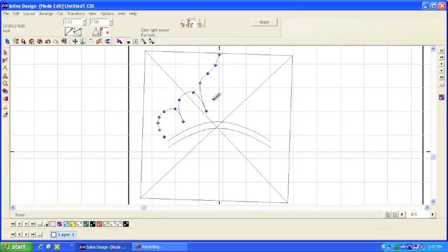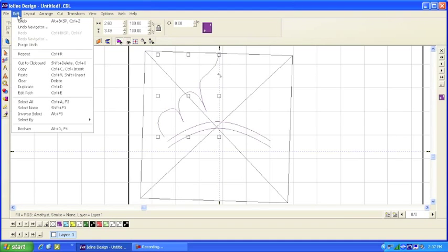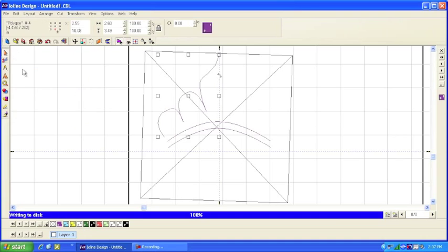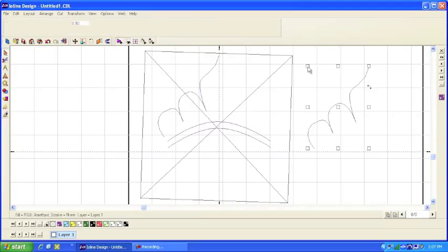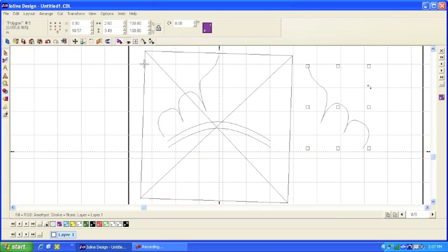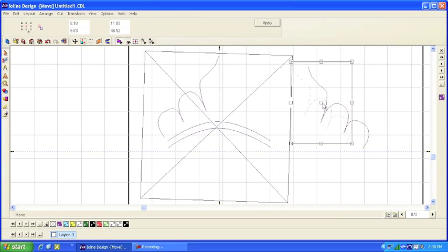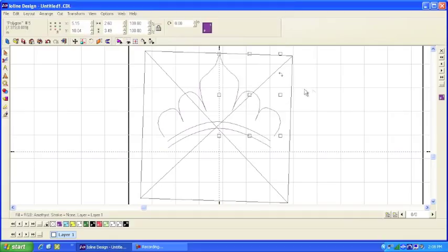Now, when I've settled this particular image, or this vector, in the shape that I like, I'm going to copy it. And then I'm going to come over to this side of the design, and I'm simply going to hit Control V, and I'm going to place a copy of that design on this side. Go to Layout, Size and Move, and Mirror Horizontal. Now we've reversed that design, and we can bring it over and place it to the right of our previous design.